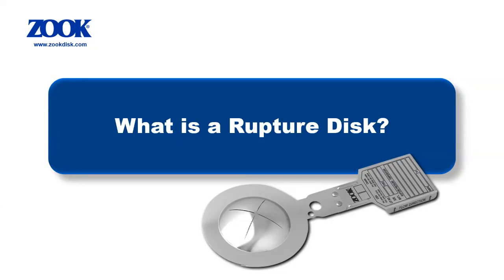Before we start to discuss what you need to know about selection, sizing, and troubleshooting, we want to provide a quick introduction to rupture disks. What is a rupture disk? A rupture disk is a safety device used in a pressure release system. It is a one-time use part using a calibrated thin diaphragm designed to rupture or burst at a designated pressure.